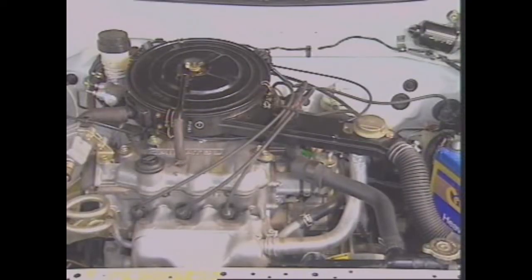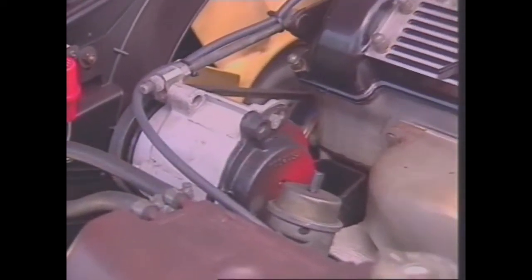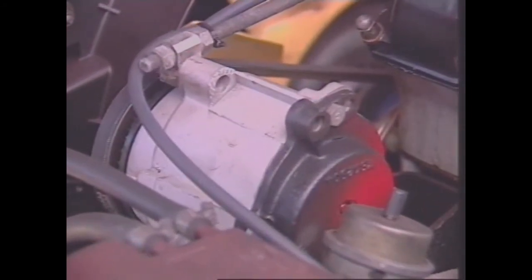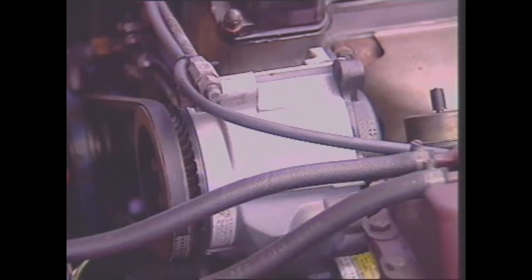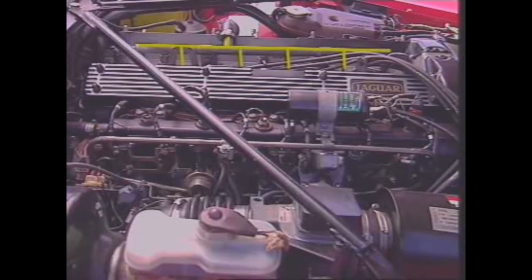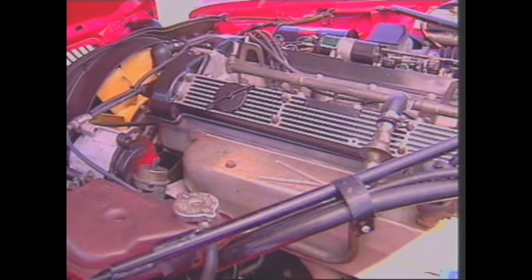This method suits engines with 4 cylinders or less, because their exhaust pulsations are further apart. Larger capacity engines may use an air pump to supply a larger volume of air. The pump is normally driven by a V-belt from the engine crankshaft and forces air into the exhaust ports. Some of the engine's output is used in driving the pump.